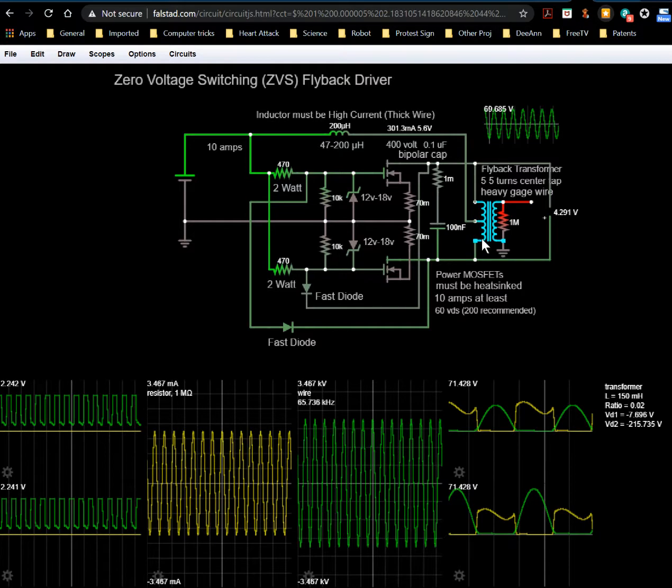So, we get like 24 volts supplied to it, a 24 volt square wave. Well, that's 48 volts when you double it. Again, this is loose, but it's a way of thinking about it to try to understand why the voltage is high. But if you get that, that's 48 volts, and if you multiply that times 1.414 to convert it to a sine wave, it becomes close to the voltages we're seeing here, which is like 60 some odd, 69 volts, for example. That actually works out about right if you do the math. 24 volts times 2 times 1.414 will come out to about the same voltage. So that could be a coincidence.